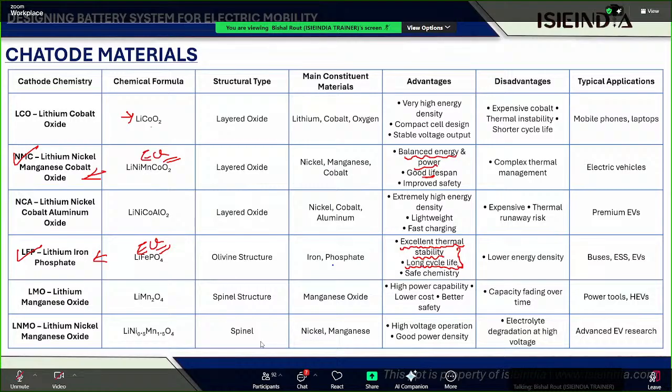At the superchargers, in winter times, they first charge, overcharge the complete vehicle battery pack, and then the battery pack generates certain heat, and that heat is very useful for the LFP in the cold environment. Then it comes to a stable temperature range, and then it will run. Else your BMS will not run, and if you directly go and sit inside the vehicle and turn on the ignition, it will never happen. So LFP has some disadvantages, but in hot weather, LFP works better.